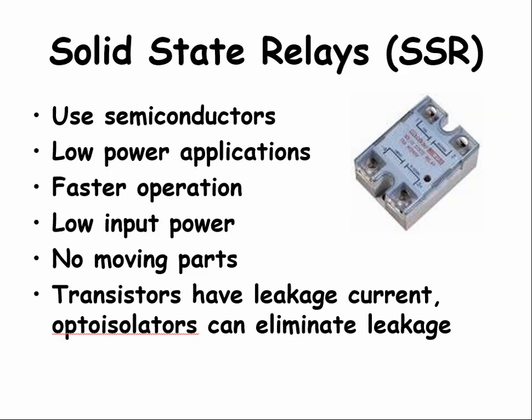It is common that solid-state relays cannot have more than 15 amps on the load side. So a solid-state relay that can handle 240 volts and up to 15 amps can control 3.6 kilowatts of power, which is around 4.8 horsepower.